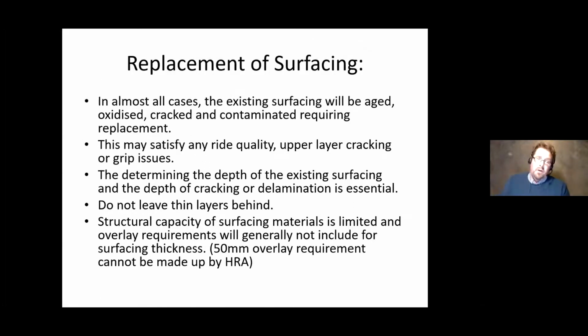So the replacement of your surfacing can be quite a difficult topic for some people sometimes, but some people just prefer to overlay directly on the existing surfacing. But in almost all cases, the existing surfacing will be aged, oxidized, cracked, and heavily contaminated. And road sweeping will only do so much. And you want to get a good bond, and you want to add structural material to structural material. And surfacing has limited structural material. Aged, oxidized, and worn surfacing has very little structural capacity.